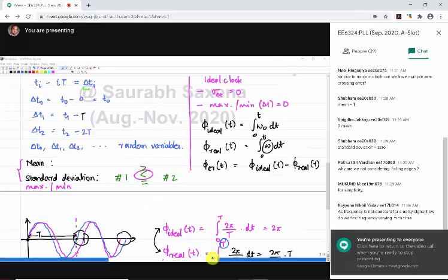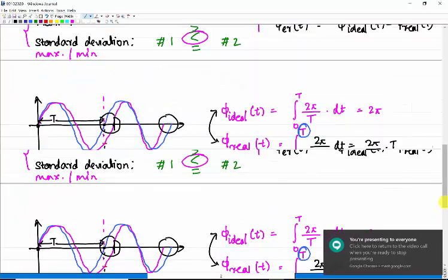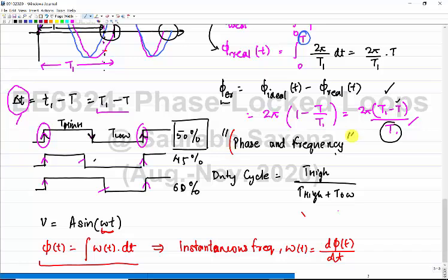Now if you look at it, what we can summarize from today's lecture is that when we are looking for a clock, the things which are important are phase and frequency of the signal, because they are more important than the actual amplitude. They are the things which fix how good a clock is, or how well we can synchronize our system in real time. Is that part clear?